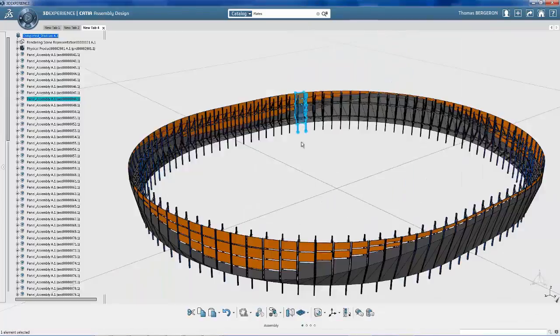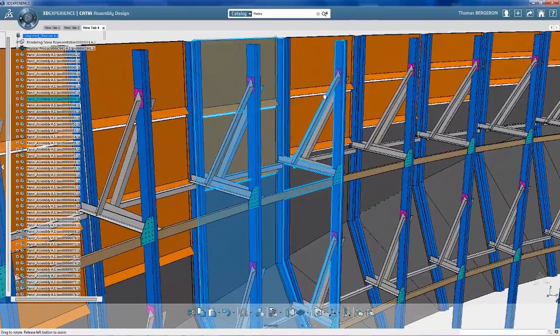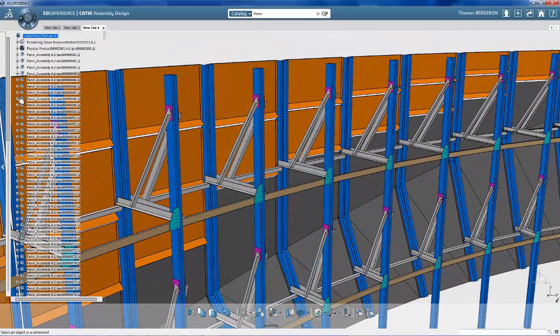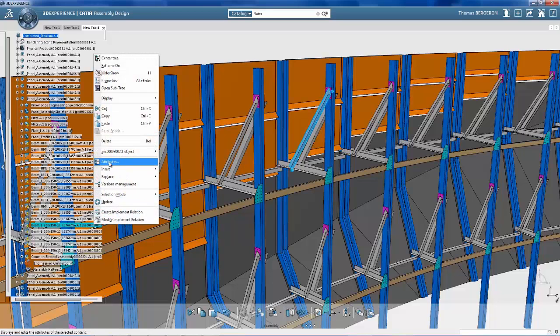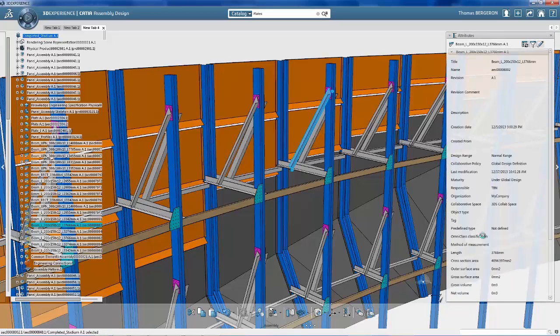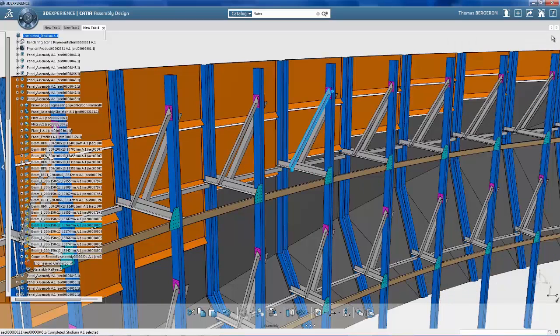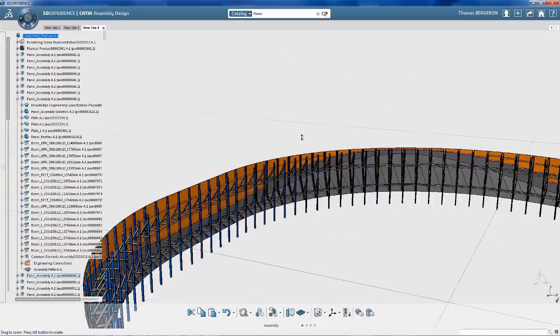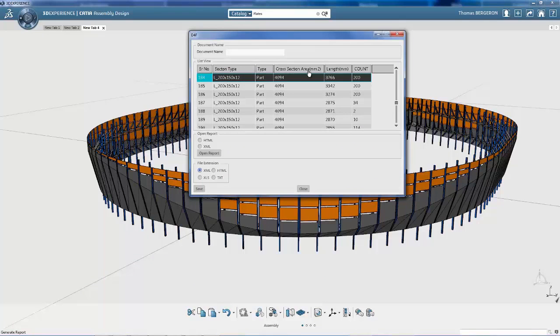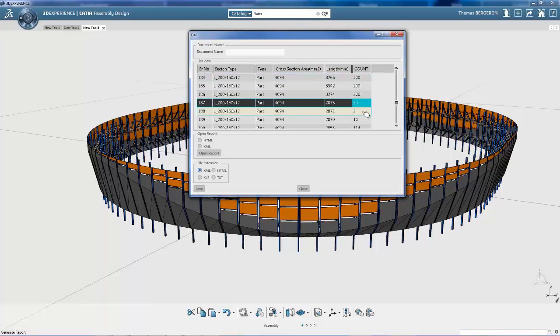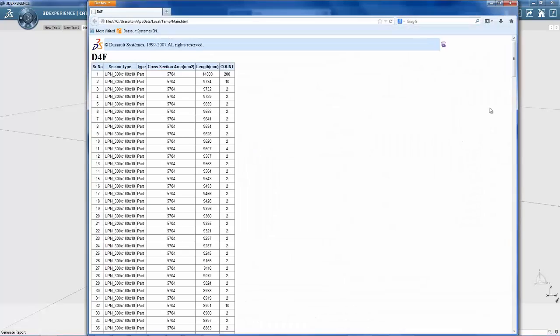Because the 3D model is defined using an AEC data model, we can add IFC extensions to objects and see specific attributes for each product. Next, the engineer runs a predefined knowledge report to extract the data needed for part fabrication. The engineer exports valuable information needed for quantity takeoffs, generating the number of panels, the size of each panel, the number of beams, and other specifications directly from the model, which enables highly accurate cost predictions.